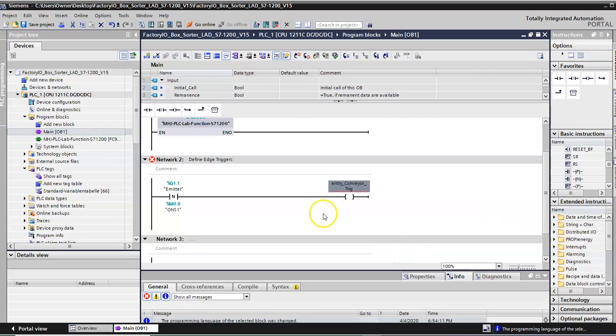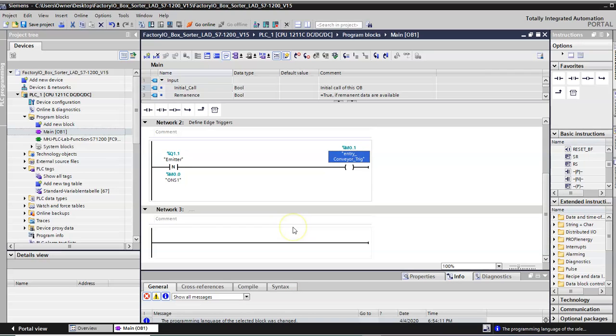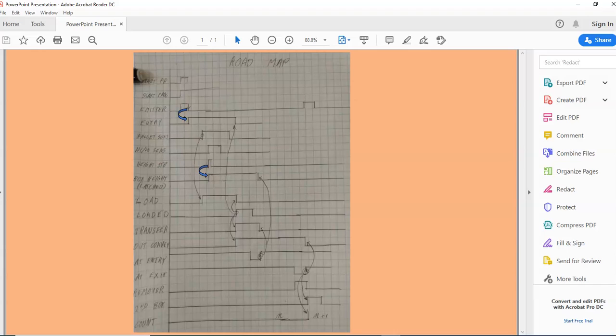And I'm going to pause this because it takes a while to do all these, but for every one that we see on here, we're using this palette sensor signal, and we're using this height strobe, which I'll explain. Basically, when the palette comes across and the boxes come across and you sense either high or low, you're always going to see a low sensor because as a minimum you're always going to see a low box. But we're going to throw that into a trigger, and we're going to use that as a trigger signal for when we want to look at it and when we want to latch in that signal.